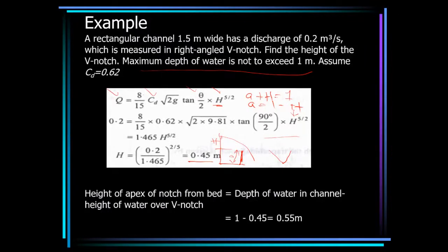So I always tell you, all these calculations, what are we doing? We are trying to find the discharge. We are trying to use a hydraulic structure called a weir to measure the discharge in streams, rivers, and channels. I always tell you the importance of measuring discharge. We measure it, for instance, for flood mitigation. When there is flooding, measuring the discharge lets us estimate whether the channel is adequate or not.